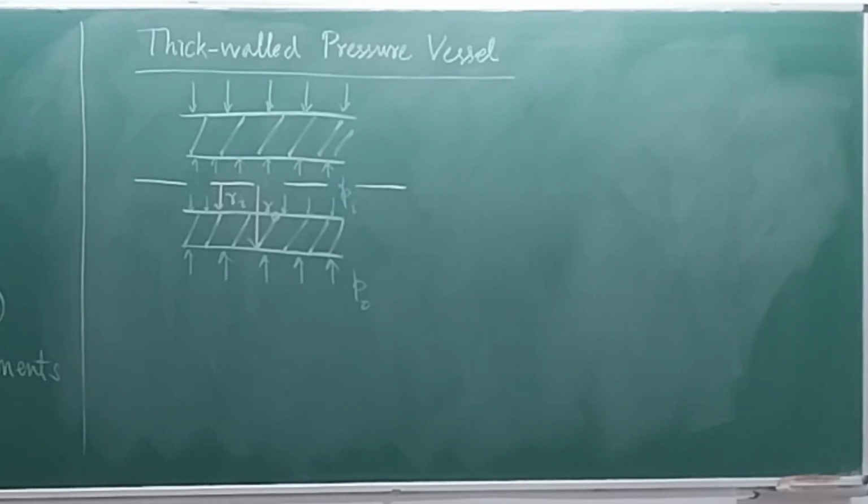Anyway, so your mess plate is not an example of plane strain or plane stress. It's like a complicated solid mechanics problem. Okay, so neither of these. There is an entire body of problems which are neither plane stress nor plane strain. It is not necessary that every solid mechanics problem can be classified as plane stress or plane strain. Okay, but many can be.